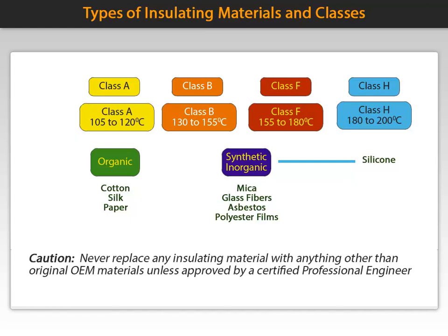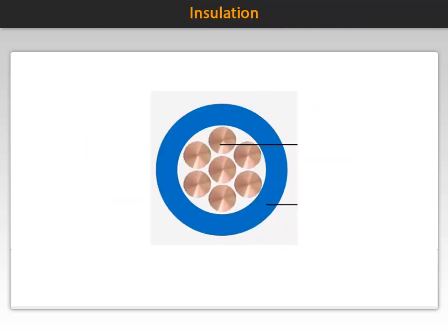Some words of caution. When servicing equipment, never replace any insulating material with anything other than the original OEM materials unless approved by a certified professional engineer. Insulation plays a vital role in protecting equipment and personnel.